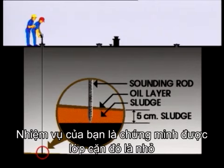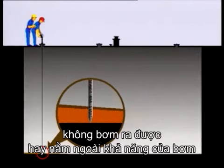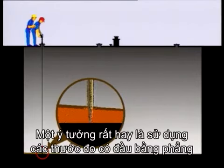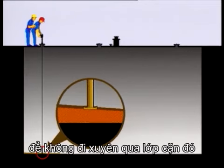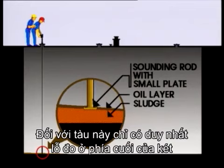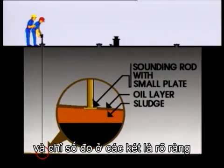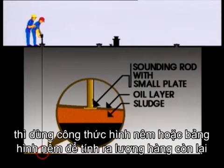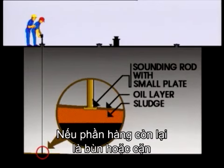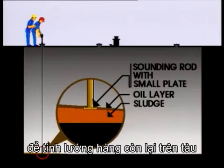Your job is to prove that the findings are negligible, unpumpable, or out of reach of the vessel's pumps. It's a good idea to use a rod with a flat end to avoid penetrating the sediment. In this vessel there are only vapour control valves in the aft end of the tanks. If there is a discussion about ROB and the dip clearly indicates liquid, use the wedge formula or wedge table to calculate remaining cargo. If the dip indicates sludge or sediment, you should also suggest using the wedge formula to compute ROB.